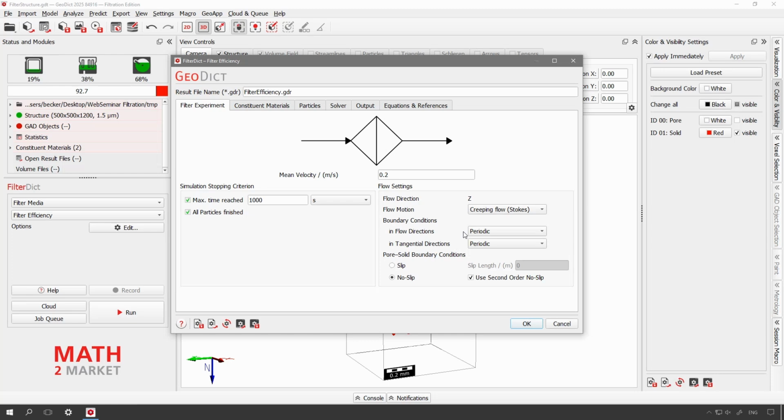In general, if you're unsure, always select the fast flow. This will always give the correct result. Fast flow will also give correct results for slow flows. It just takes longer to compute. And you can speed things up if you know initially that the flow is slow enough.